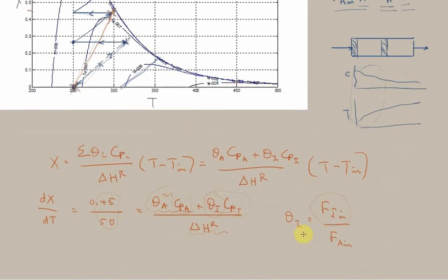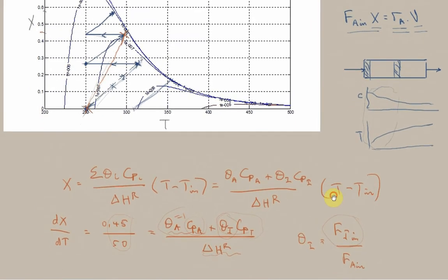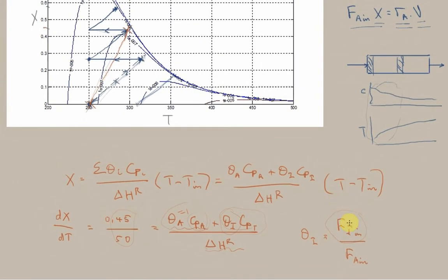But of course, if we are increasing the molar flow rate of component I, there are certain costs associated with that. And so we have to consider those costs and see when it starts to become unfeasible and so on. So hopefully to accomplish such a change, this is a feasible flow rate for component I. And remember, I is not being used up in the system. It's an inert, so it can simply be recycled. So it's not unreasonable to say we could use high flow rates of component I through the system.